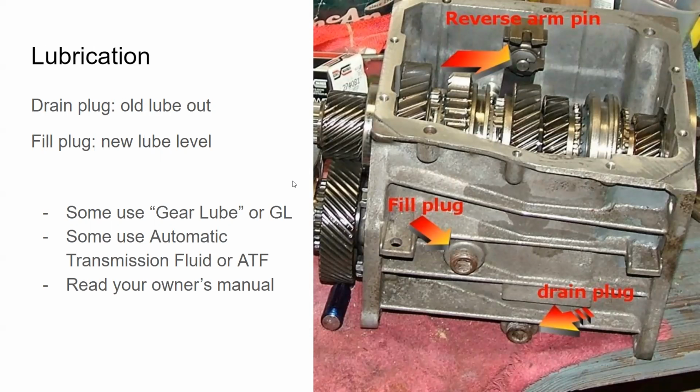Lubrication for manual transmissions. Some of them want a gear lube. Some of them actually want automatic transmission fluid. It just depends. You have to read the owner's manual. Some don't care.